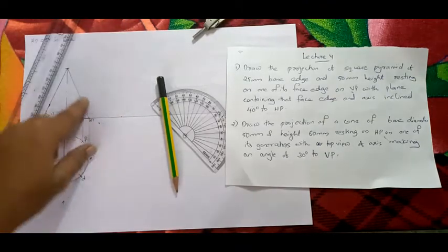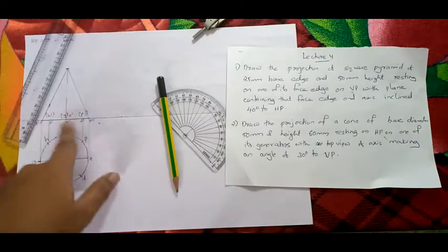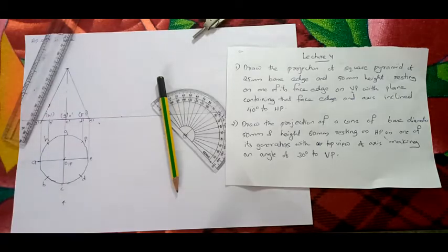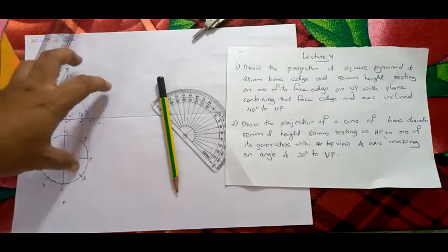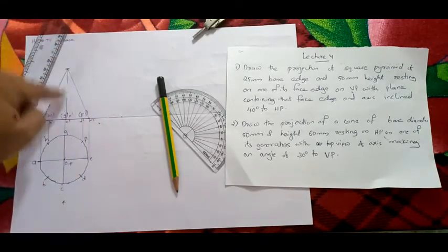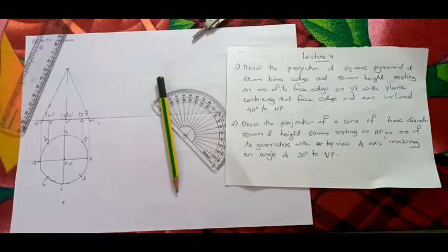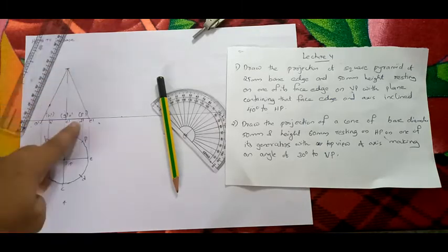Now see, this surface is actually made up of infinite lines, right? If you are rotating, it's a solid of revolution, so this front view of your surface, the surface is made of an infinite number of lines, and each line is called a generator. A generator is a line which connects the apex to the base.